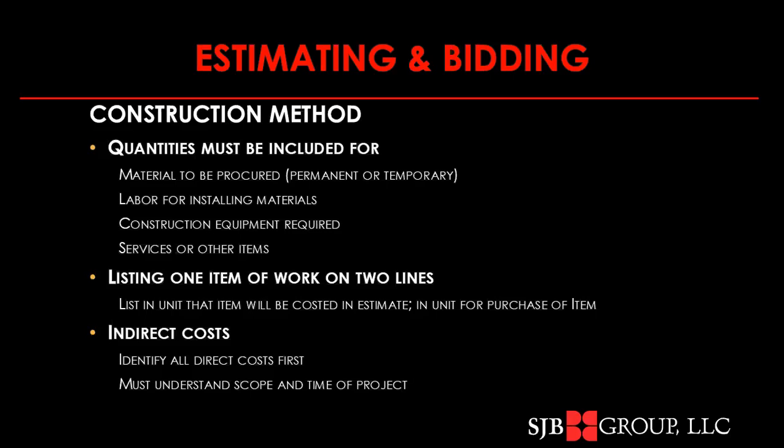One approach may require that you set up a yard on site, while another approach would not need you to provide the indirect cost for that yard. Whereas another approach, just-in-time delivery method, for instance, would not need that storage yard to be developed or priced.